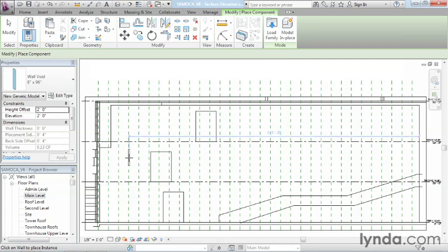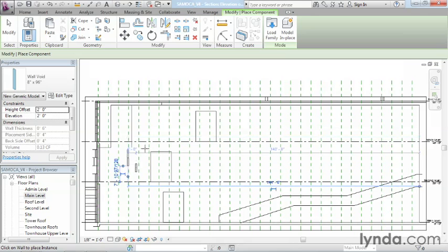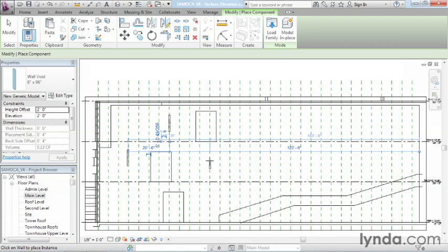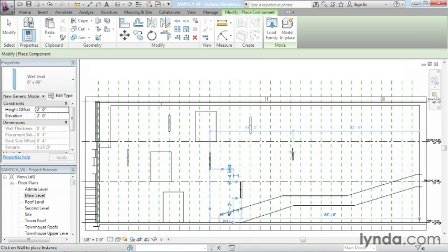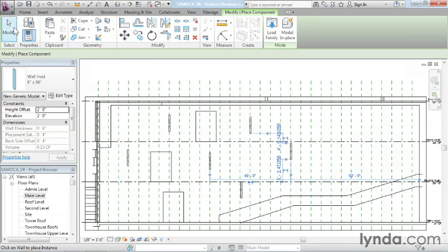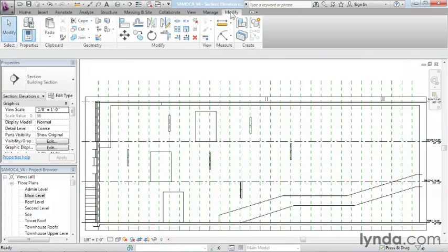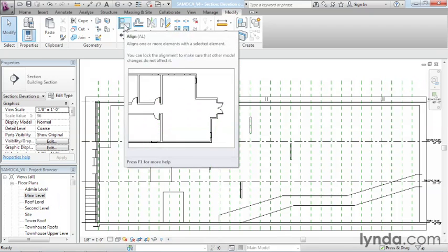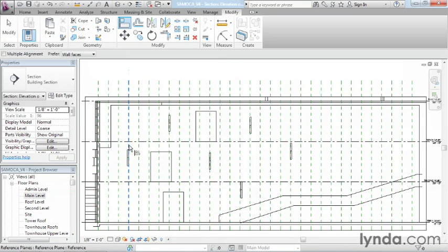and you can kind of see that you can place this really anywhere you want to go. What you do is you sort of place it nearby these grid lines. Maybe I could place a few of them like over here and over here and over here. And then after you've done however many you want of this size, and again, avoid this area here where the stairs are, you cancel out of there, you go to the Modify tab, and you use your Align tool, and you just align from the reference plane to the center of the void. You can even lock those if you want to.